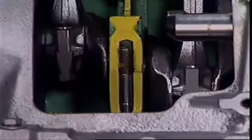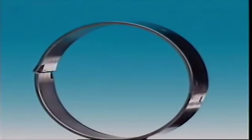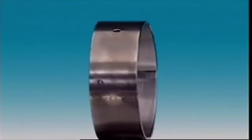Bearings need a difficult mix of properties. They must be hard enough to resist wear, but soft enough not to damage the shaft. The soft bearing surface also allows any hard abrasive particles to become embedded in the surface. They can become so deeply embedded, they're prevented from touching the rotating shaft by the film of oil. It's the mix of metals, tin, lead, copper and others, into an alloy that makes this combination of hardness and softness.